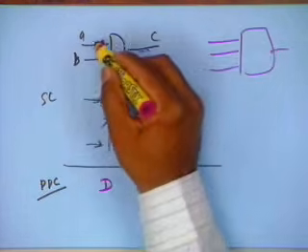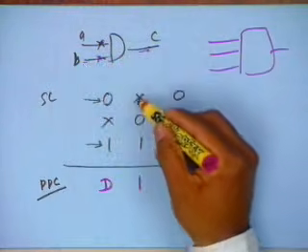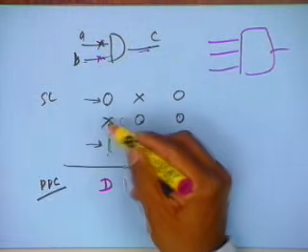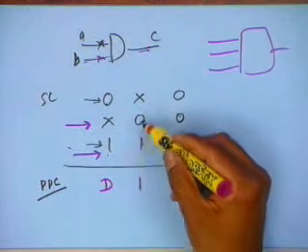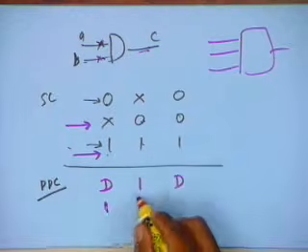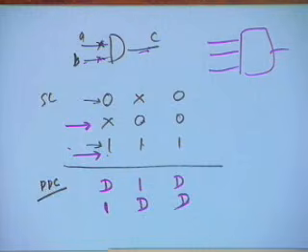So I have managed to get the fault here to the output. Let me look at the case where the fault happens to be on B. I will look at a row in which this particular column is 0 and another where it is 1. I have this row where this is 0 and in this one this is 1. I take the cross intersection of these two. When I take the intersection, I get 1 D D. So this is 1DD and that's D1D.